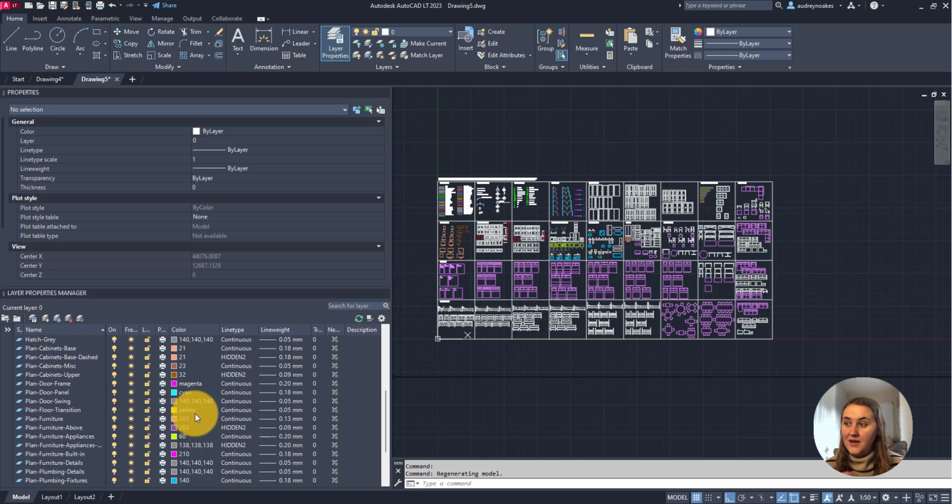It also means your drawings are more organized. Especially for interiors, if you have a floor plan with all the walls and all the doors, but also all the furniture and all the finished materials on the floor, all in one drawing, sometimes it's going to be really important that you can say, okay, let's make a drawing with just the architecture. Let's make a drawing with just the furniture and the architecture. And then let's make a drawing with just the finished floor materials represented, no furniture. You want to be able to turn these on and off,